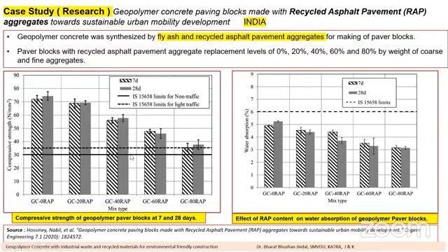Now the limits: there is a dotted line as well as a hard line, two lines mentioned as per the restrictions of IS 15658, which is limiting for non-traffic type of pavement as well as light traffic type of pavement. Research clearly indicates that even with recycled aggregate, you can develop geopolymer concrete with sufficient, quite greater strength than the minimum required as per the IS code provision.